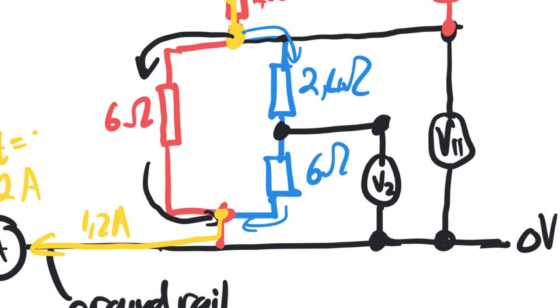And the reason why the parallel resistance, the effective parallel resistance, and I use that old symbol that we used to use for resistances, so R parallel is 3.5 ohms, is because by adding resistors in parallel, we are creating extra conducting paths, which makes the flow of charge easier. So therefore, the effective resistance is less.